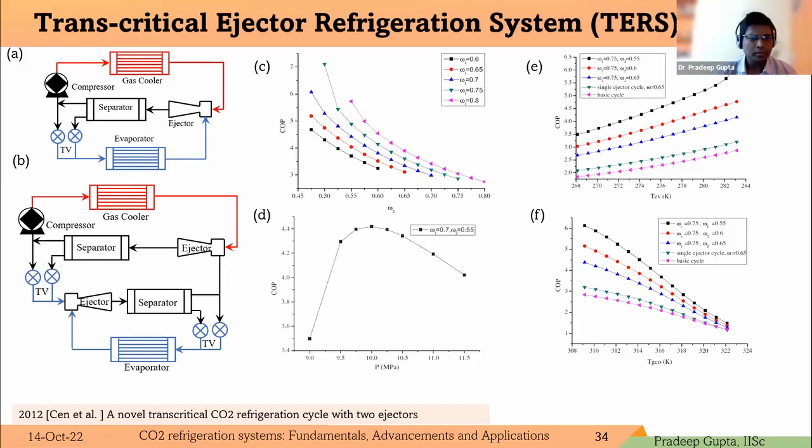But you are using that energy also to compress a little bit of vapor that is throttled. That is useless. So it's better to control the compressor such that the second throttling is always 0, depending upon the ejector capacity that the compressor is taking.